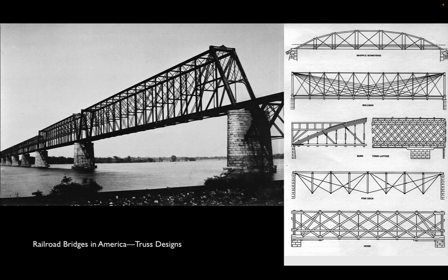So in the United States, the sort of standard issue rail bridge becomes the truss. And the truss bridge is a way of breaking the span down into hundreds of smaller pieces, all of which can be put onto rail cars fairly efficiently, taken out to the end of the line where the bridge construction site is, offloaded and pieced together by relatively unskilled labor, right? It takes iron workers, but the iron workers basically just have to know which parts to bolt together, and they can build the bridge even hundreds of miles remote from the nearest engineering firm or manufacturing facility.